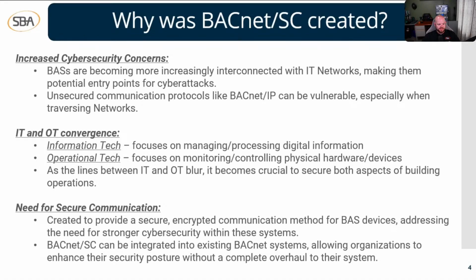And then the next point is BACnet SC can be integrated into existing BACnet systems, allowing organizations to enhance their security posture without a complete overhaul to their system. So there's ways that you can integrate your BACnet over IP devices into BACnet Secure Connect. It's basically just adding another level of security onto our BAS systems. So we needed more secure communications, and that's why BACnet Secure Connect was created.